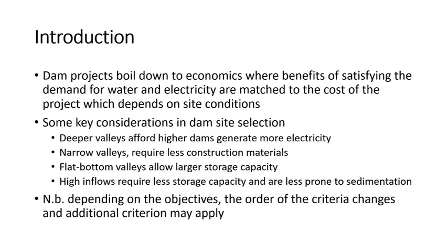Narrow valleys, of course, require less construction materials. Flat bottom valleys allow larger storage capacity. And high inflows require less storage capacity and are less prone to sedimentation.